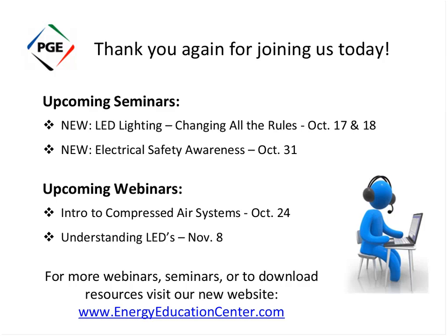So let's say in the preheat tank on a cloudy day, the incoming water temperature might be 50 degrees. You might only see 65, 70 degrees coming out of that preheat tank on a cloudy day. On a very hot, sunny day, you could easily achieve all of your heating needs. So you could easily see 135 degree water coming out of that preheat tank.